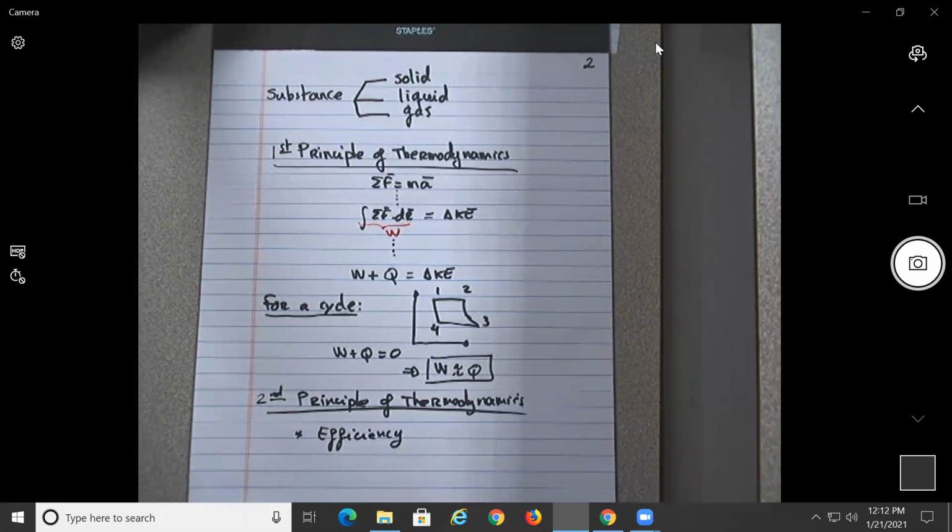If you think about it, maximum temperature, minimum temperature, no? The farther away they are, the more efficient is the system. The closer they are, the less efficient your engine is, okay? And you agree with me that the only way to have an engine that is 100% efficient would be to have absolute zero, which is not going to happen, no? Okay? So nothing can be 100% efficient.